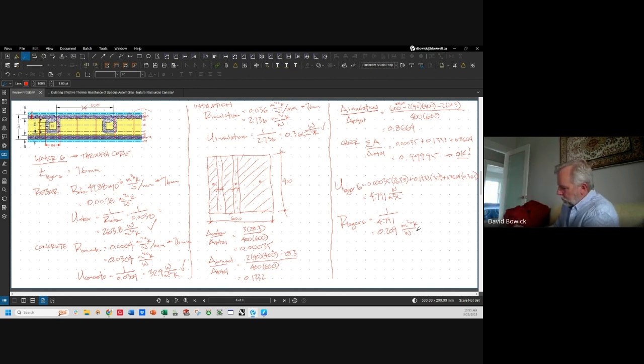Okay, I'm going to check this one more time because these calculations are easy to get wrong. 0.00035 times 263.8 plus 0.1332 times 32.9 plus 0.8664 times 0.365, 4.79. Invert that. Get an R value of 0.0209. There's layer 6.